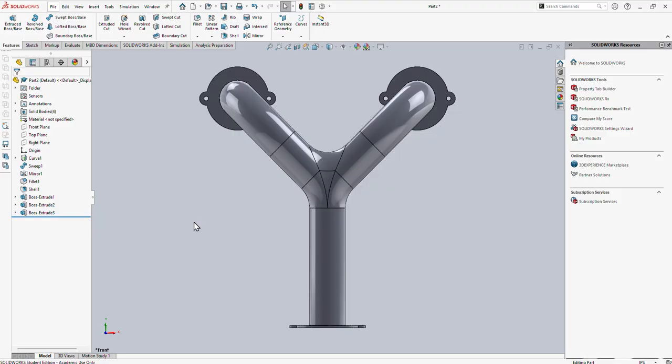We have a hole here, and that hole has threads in order to thread on our O2 sensor. And for that we need some surface area too, right? We need some solid face here. We cannot just drill on a 1/8 of an inch tube thickness and attach our O2 sensors over there, right?